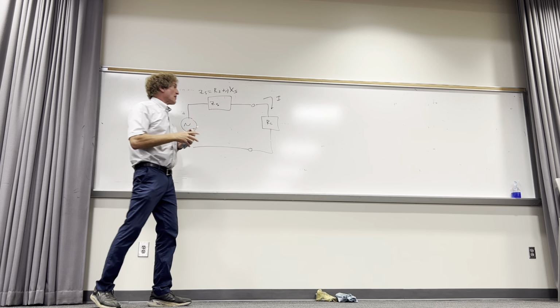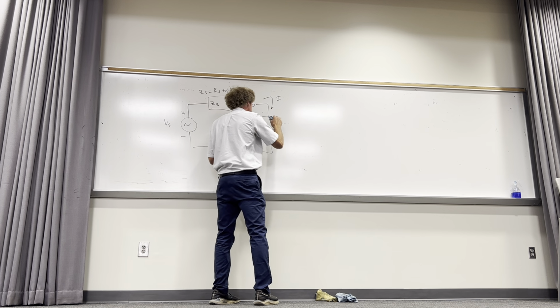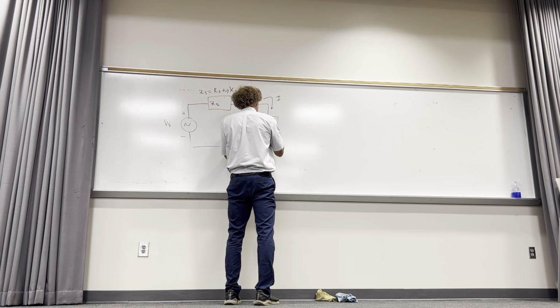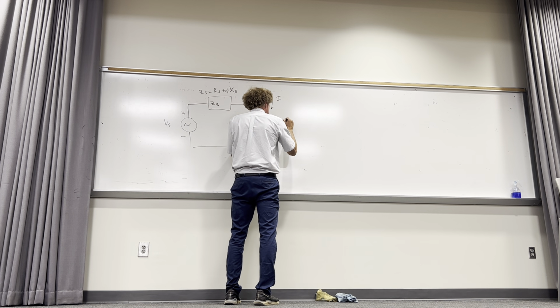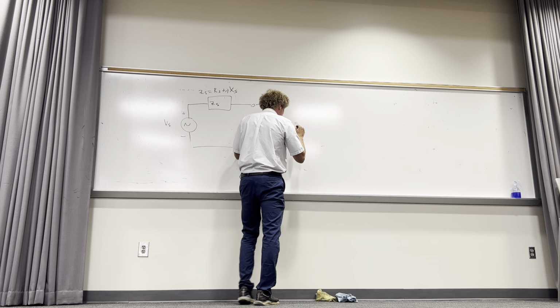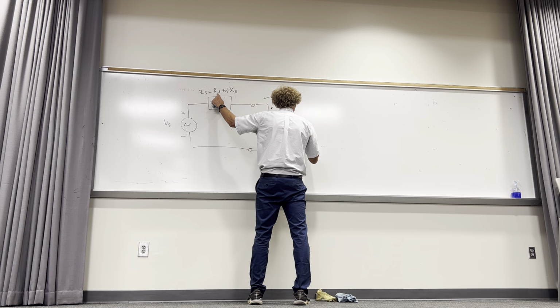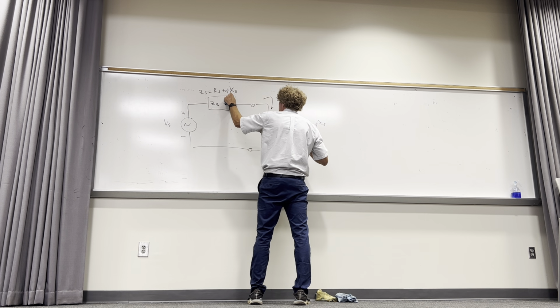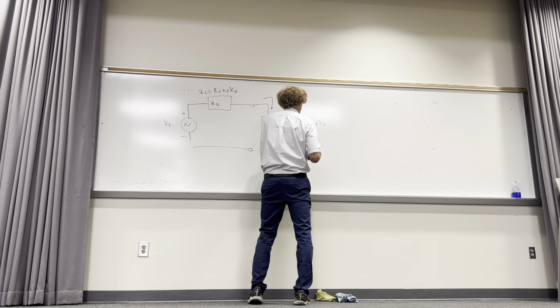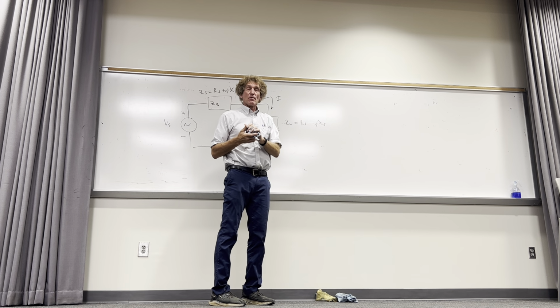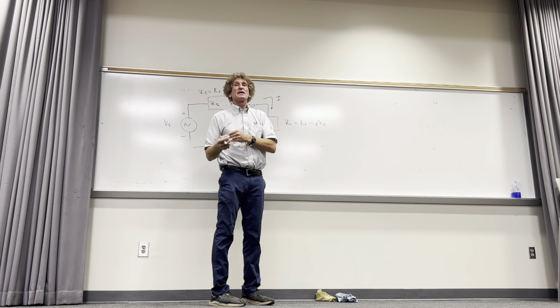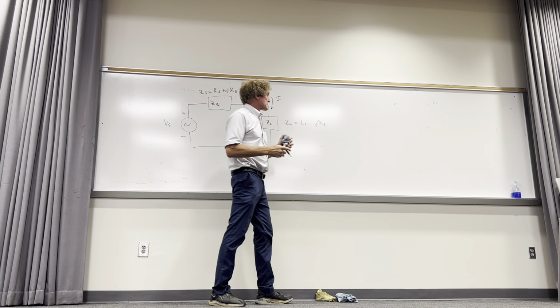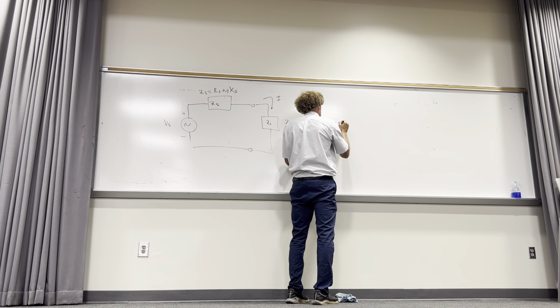You will find that the load impedance, and I'll call it Z load, when ZL is equal to the same magnitude here, only minus JXS right here. So if that's a positive J5 ohms, this will be a minus J5 ohms. That's called the conjugate of the source impedance. The symbol for this would be ZS and an asterisk.